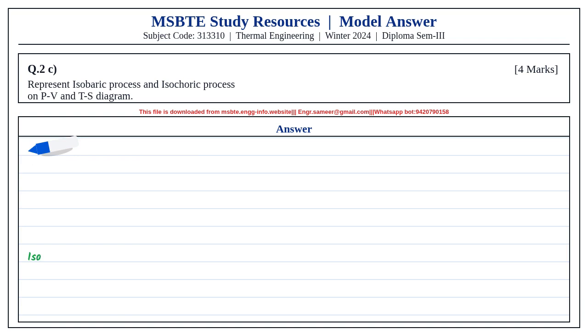Since volume remains constant, pressure divided by temperature remains constant. Therefore T2 is equal to P2 by P1 multiplied by T1. Substituting values, T2 is 924 Kelvin or 651 degrees Celsius.